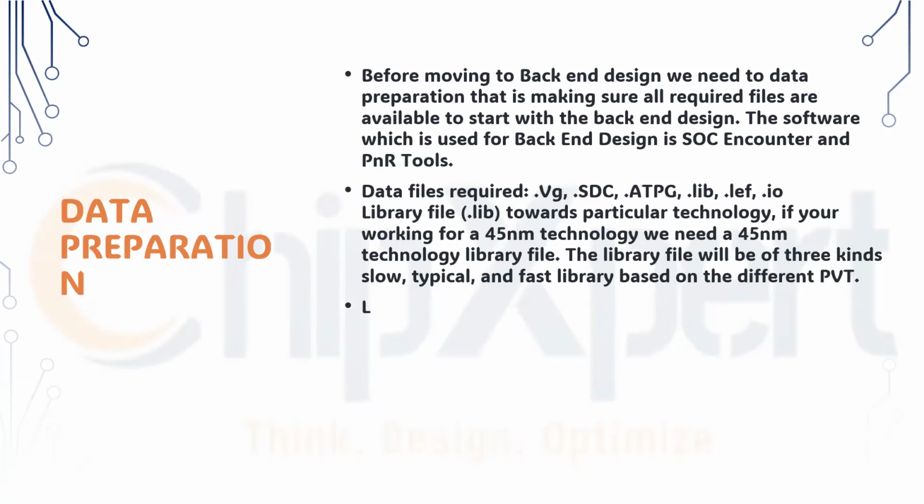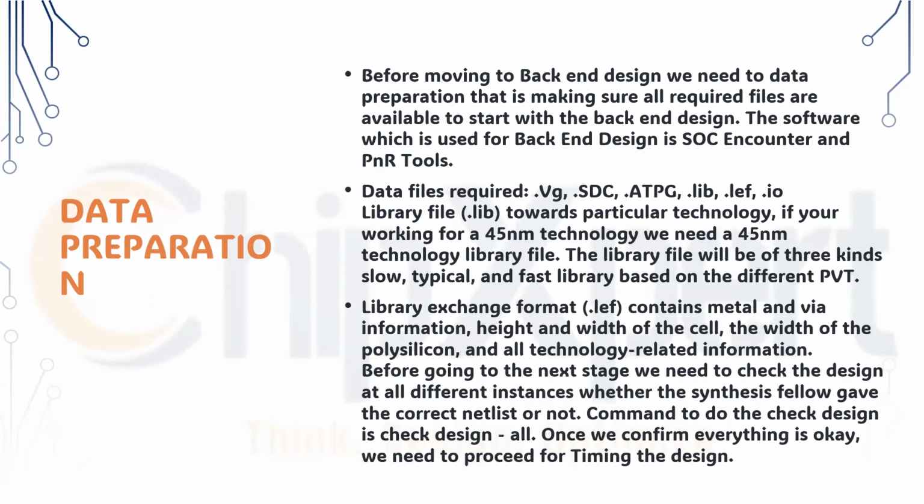This is how DFT works, and coming to the inputs for the next stage, the backend. At the backend stage, once you have completed the front-end process, we have a logic. First, the RTL team creates the required logic in HDL format, and it is synthesized. For the synthesis data, we insert the DFT logic. That logic is then submitted for the backend design. So what files are required for that? Basically, for the backend team, the physical design starts, and the layout team starts their work.